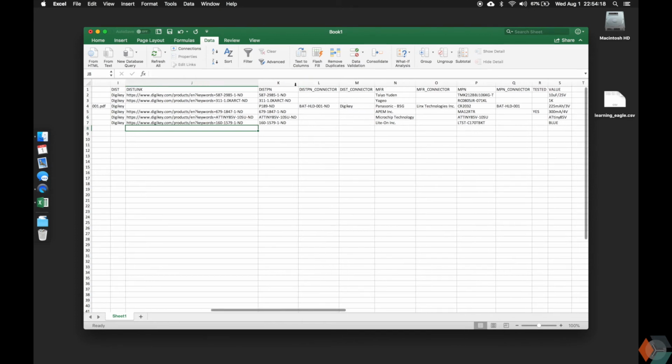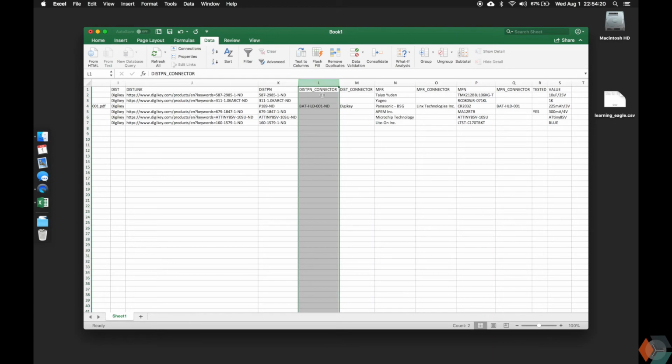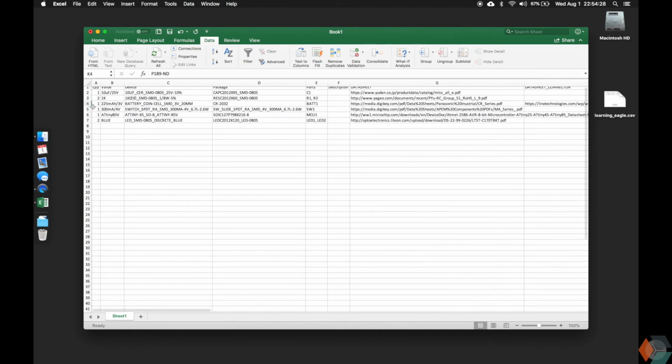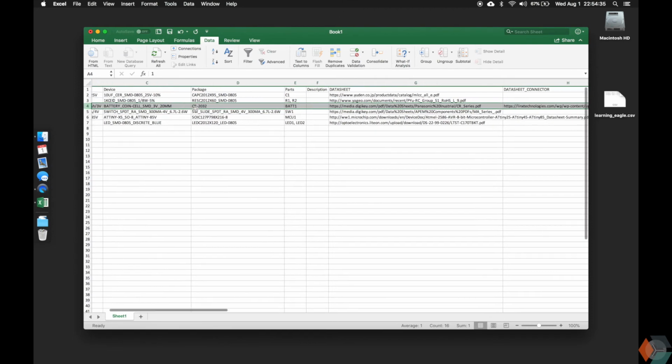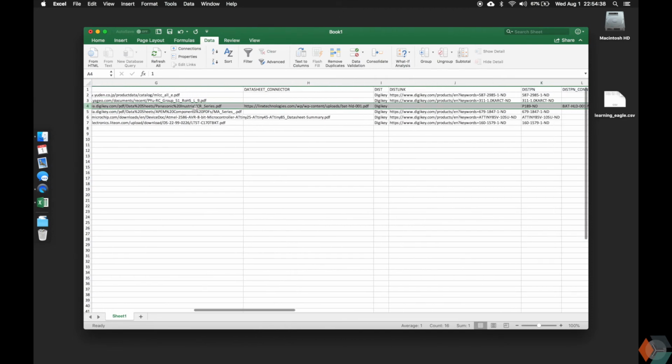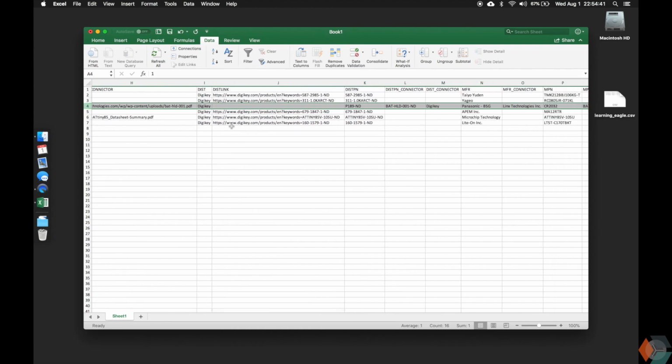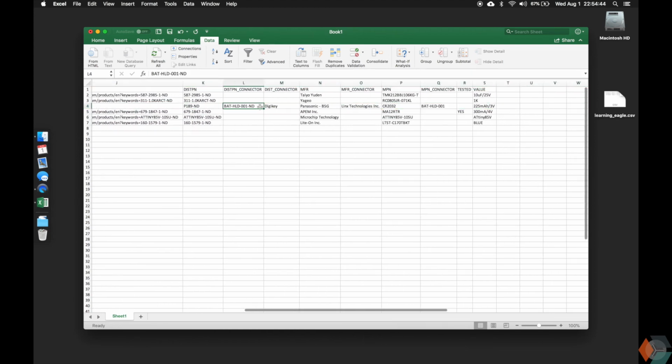You're going to notice some of these have this part number with an underscore and then some other name. And this is to denote, for this particular part, the coin cell battery, that this is the battery itself, the CR2032, and in addition the connector, which is what we saw in the 3D model, what we place on the board. So this is so that we can place both at the same time.